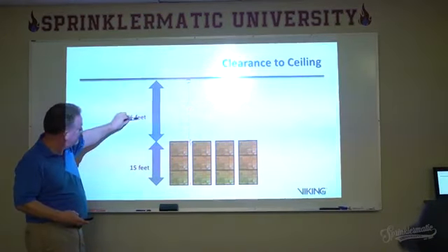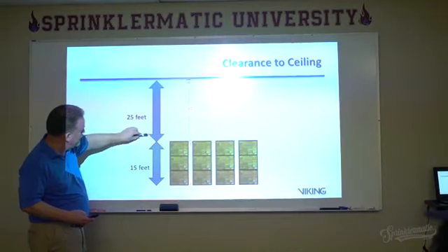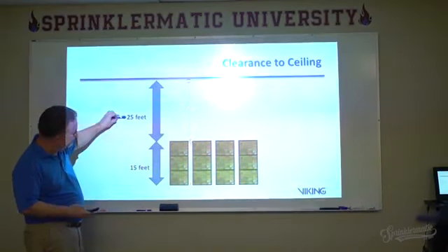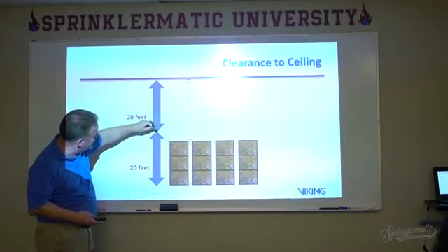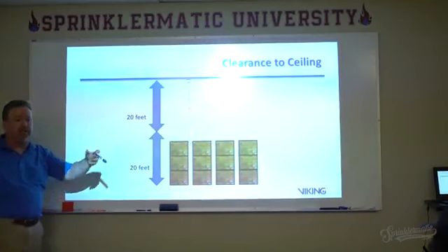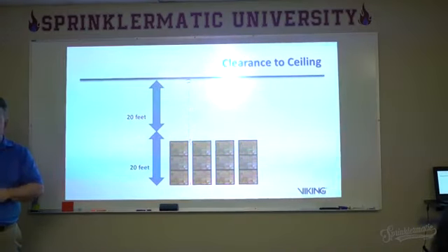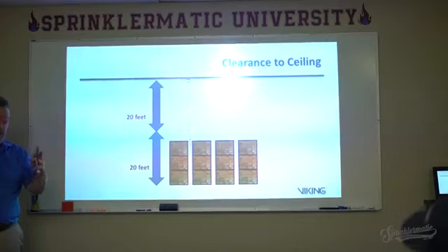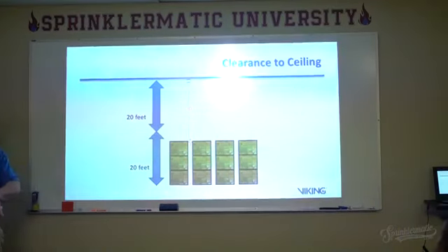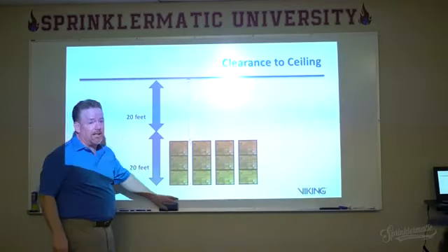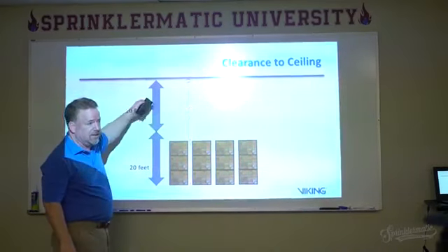25 feet? 25 feet here. So I would need to go up to 20 feet of storage. I would have to actually design this as though there were 20 feet of storage. Now that means something when we get into each of the chapters, okay? Because remember, the design of your storage sprinkler system is based on, one of the things it's based on, is that storage height. So even though there's only 15 feet of storage, I have to treat it like it's 20 feet of storage in this case.